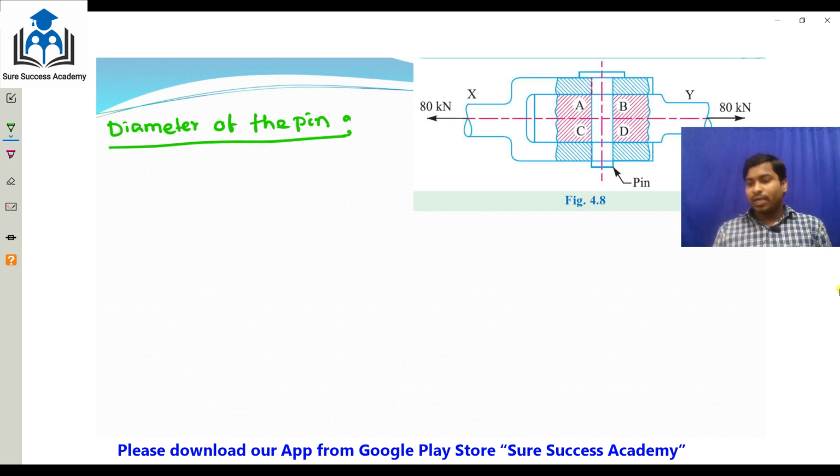Suppose dp is the diameter of the pin. Since the tensile load P is acting, the pin will have two sections, one AB and CD section. Therefore, the pin will be in double shear.